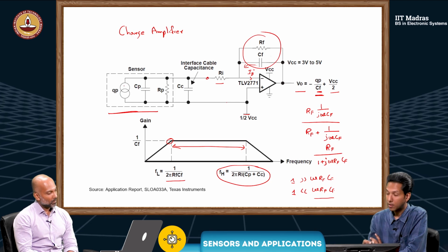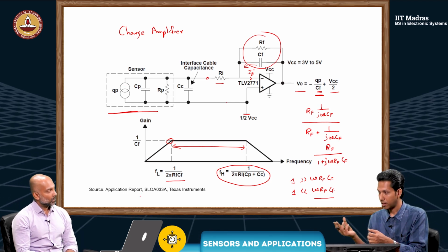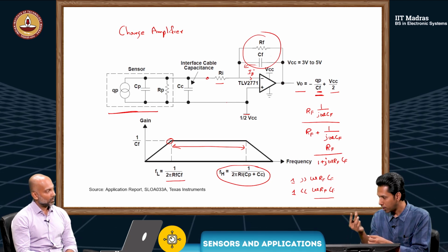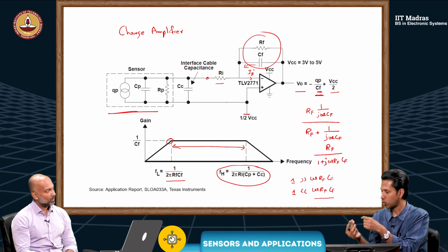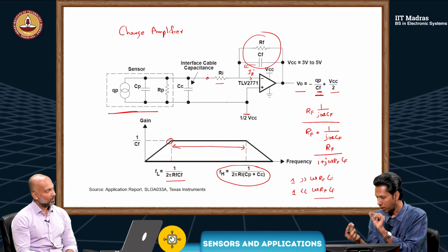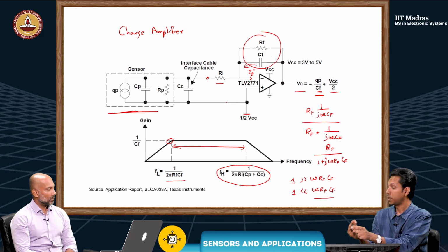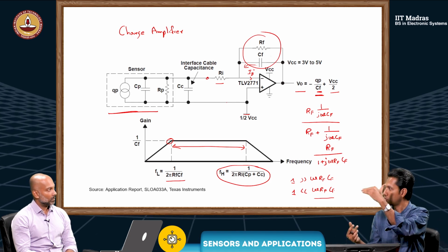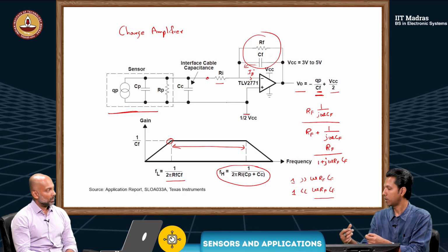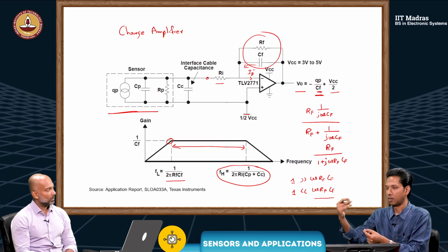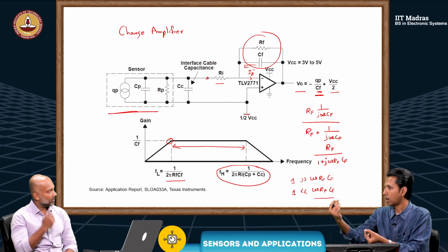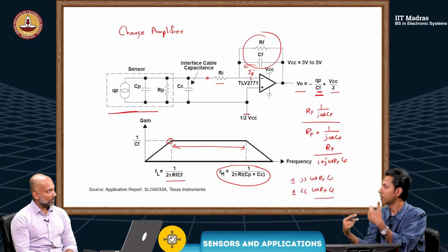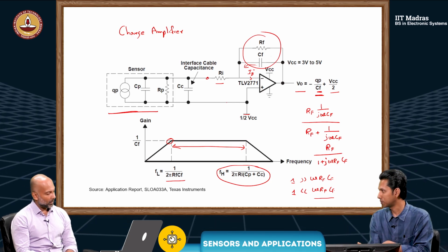We have also talked about impulse. In the case of a gas lighter, you are giving an impulse. You are slowly pressing, but once it reaches a threshold, a mass is moved and hits the piezoelectric stack. Inside there are many layers of piezoelectric material. You give a hit, all these voltages add together and become a very large voltage. It creates a spark, a small breakdown of the air between the center point and the outside ring, and that is how the spark is formed.